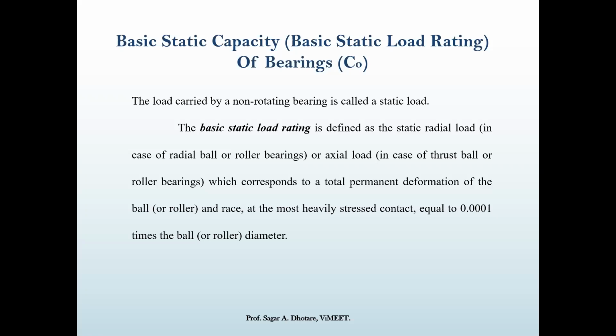Okay, so the basic static capacity, or basic static load of the bearing, is defined as the static radial load, or axial load for a thrust bearing condition, which corresponds to a total deformation of a ball and a race at the most heavily stressed contact equal to 0.0001 times the ball or roller diameter.